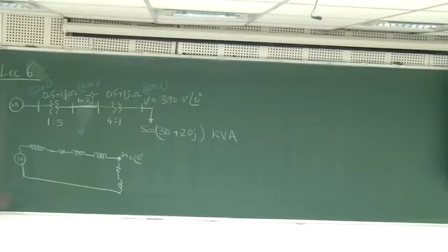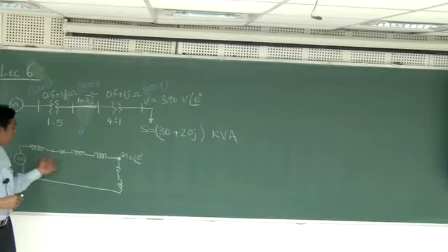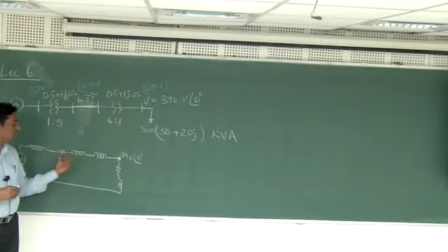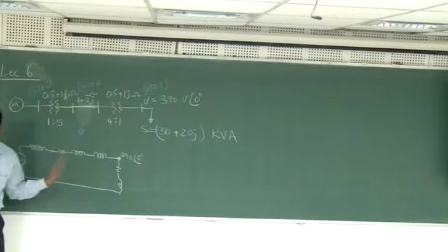It's a simple circuit solution. So there are no transformers in this. There is only one reactance of the transformer, which is an approximation of the transformer. So the advantage here is that you can add all this X, this R, this entire thing is one impedance, and then this is another impedance. You can just solve it more easily using this kind of structure.